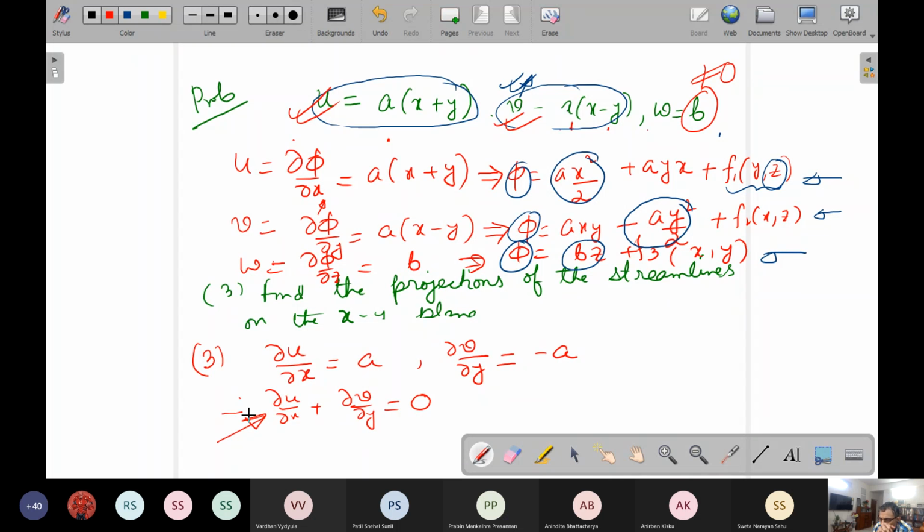This is the condition for incompressibility or the kinematic constraint for incompressibility for a two-dimensional situation, it boils down to this. So that is true that for two-dimensional and incompressible flow, this is 0. But what may not be true is that if it is 0, it need not necessarily be two-dimensional and incompressible. Okay. So this second part, which I have just told, is something which I am dead sure none of you have ever thought of.